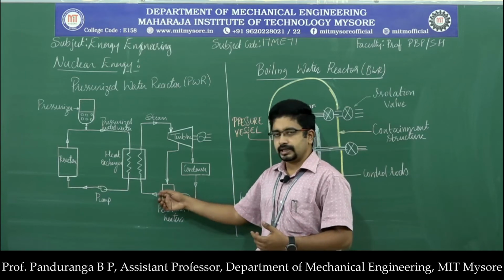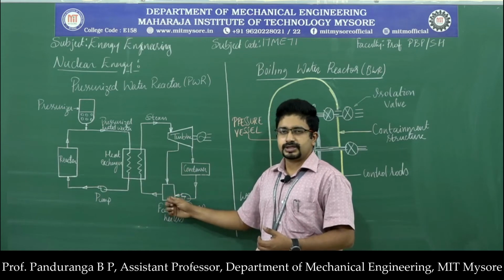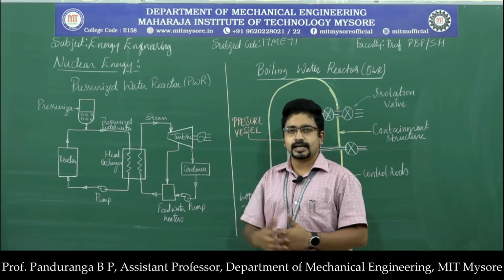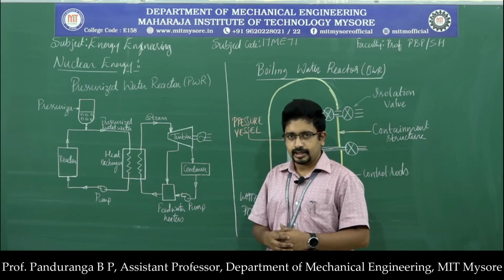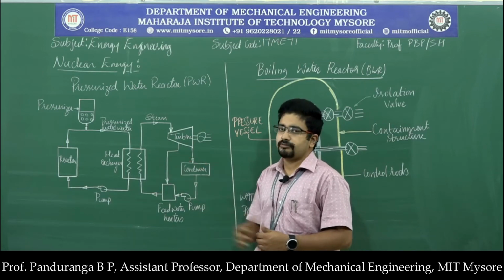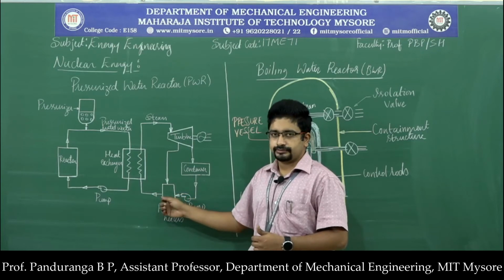This would be designed in such a way that the amount of steam extracted will be sufficient to heat the water to reach its saturation temperature. And we need to make sure that the pressure of the bleed steam will be slightly larger than the pressure of the water here. Okay.